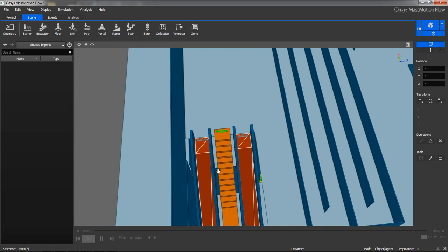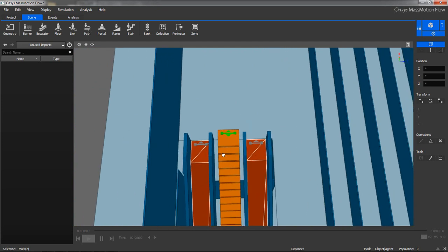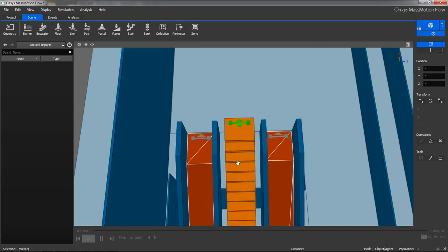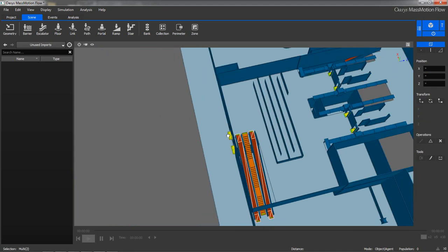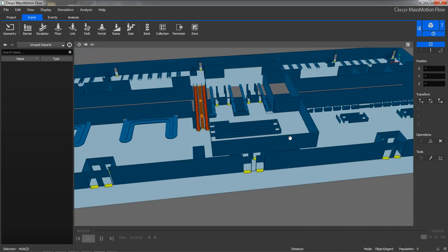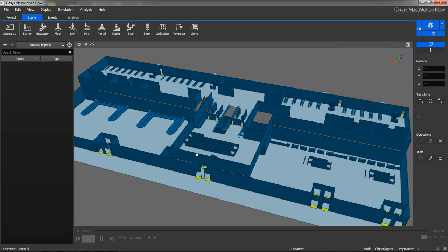And you can use Shift and Control as modifier keys for your selection state, where Shift always adds things and Option acts as a toggle, and Control acts as a toggle and Control Shift deselects. So we'll go to Vertex selection mode here and select those. And we'll just move them until our lines go green. And now we have a fully formed set of geometry from our IFC import.